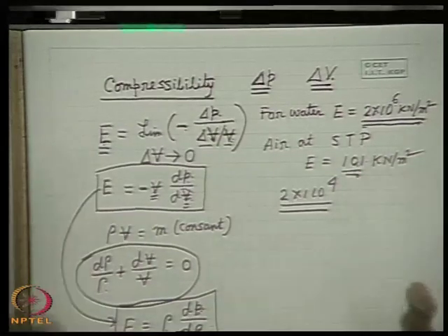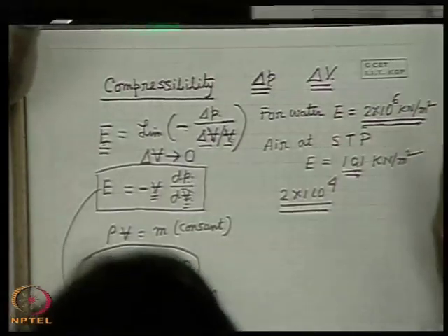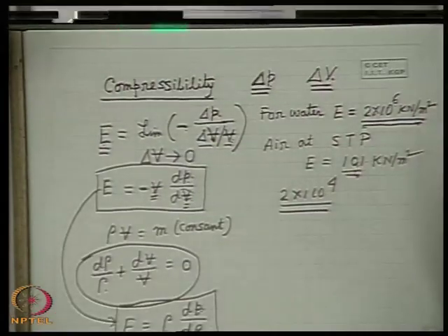Well, it's clear. Now the question comes in engineering applications, a very interesting question. We define the substance fluids by the compressibility parameter, we apply the pressure and we find out the change of volume and density, and we find the value of bulk modulus of elasticity. Qualitatively we see that if it is very high, with a very high pressure the change is very small, so it is less compressible, it is incompressible.